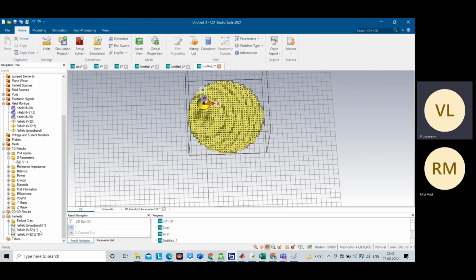Before we go for radiation pattern measurement, we have to see the theoretical. The feed location in simulation will be different from the measurement one, because first you have to optimize the matching by moving here and there. Once you are getting perfect matching throughout the band, you lock the location and make the mounting structure properly. Then you go for the radiation pattern measurement. That's how we go.